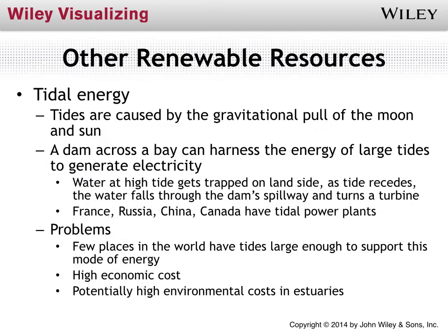And then once that water has filled, you shut the dam, so it's holding the highest level of water, the high tide volume, inside the bay. Then when you get to the lowest tide on the outside of the dam, you open up the dam again, and now you generate electricity again, except the water is going from the bay back out to the ocean. So theoretically, twice a day, you can generate electricity going both directions to spin turbines to make electricity.